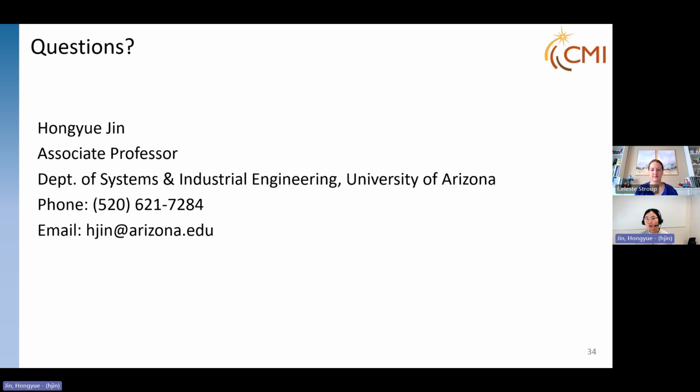So we learn this as we go. Most technologies that I have worked with are lower TRL. As they advance in TRL, they will be experimented with at a higher processing volume and we get new information about the efficiency. One piece of information I heard was that in the lab, stirring for 15 minutes will fully dissolve the rare earth, as opposed to when we go into thousands of gallon scale, it required 2 hours to do that. And how do we estimate those efficiencies?